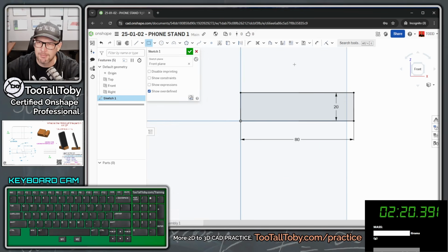And so now we can press the S key again and jump into the line command. Now, when you go to create this shape with the 3 lines, the one thing you want to avoid is picking up on midpoint. You don't want to pick up on midpoint. So just move over a little bit to the right here, single click, move your mouse down in this direction, single click.